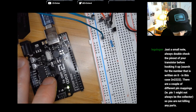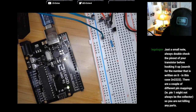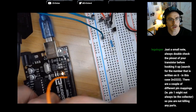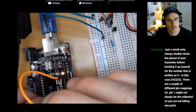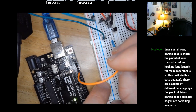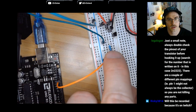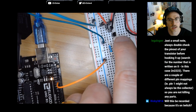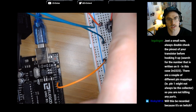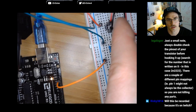All right, so what I'm going to do, I'm going to grab some wires here. Pin 13 on my Uno is just turning off and on. And I'm going to connect that to this 5 kilo ohm resistor. So current's going to flow from here through the resistor into the base. And then that little bit in the base is going to effectively allow current to flow from the collector to the emitter.